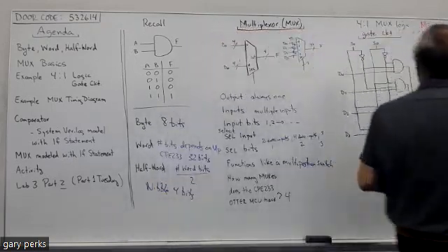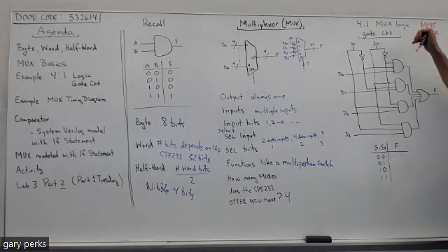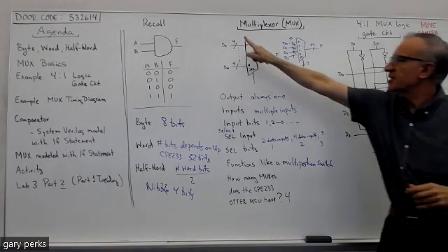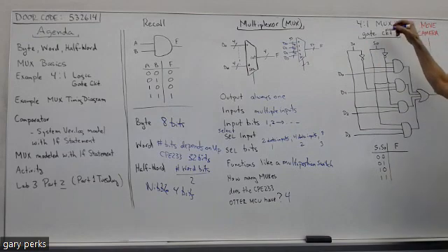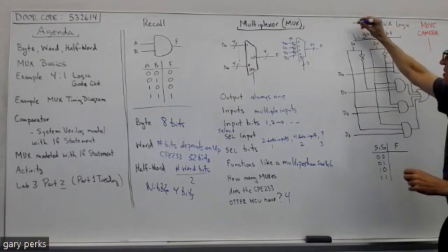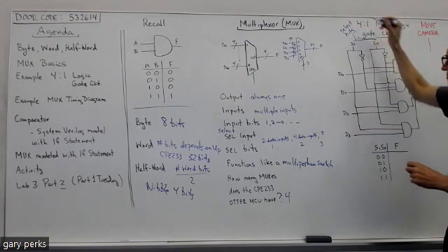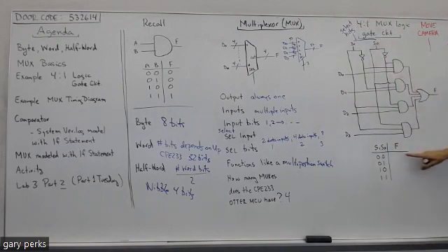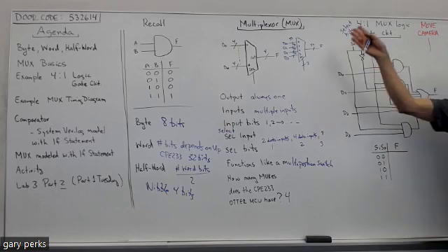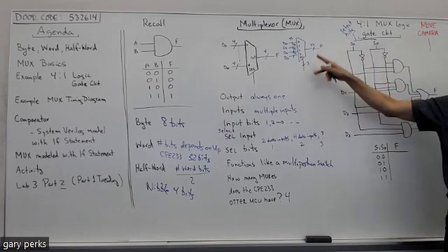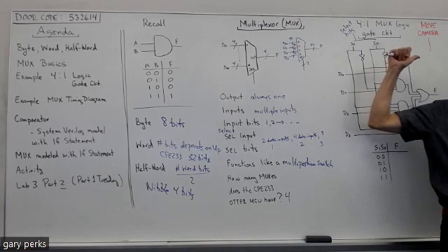Okay. And we've got these NOT gates now. You know, these are our data inputs, right? And here's our select bits. So S0 and S1, those are select bits. Okay, so we're going to fill out this truth table. I don't think we'll do all 4 possibilities. I think once we do 1 or 2, you'll get the idea. But this will reinforce what we just talked about, that these select bits determine which data gets connected to the output.